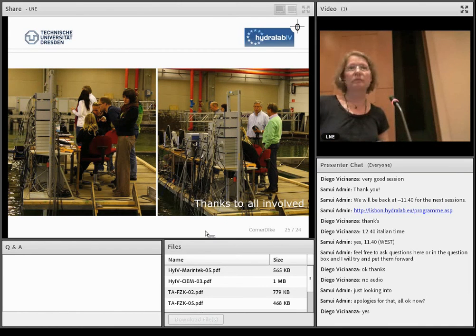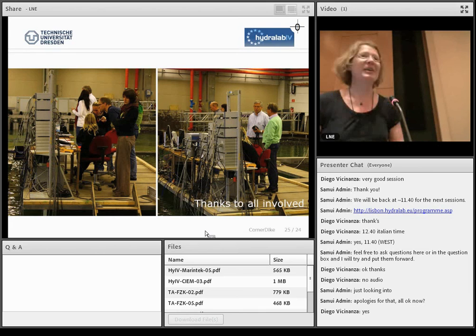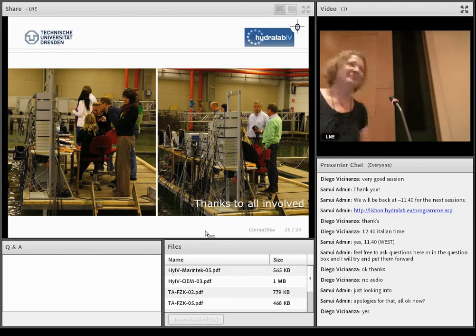My question relates to how you handle the varying water level, the storm surge level. I presume you keep the water level constant in your tests. For the run-up tests, we had only one water level of 70 centimeters, but for the overtopping tests, we had tests with different water levels, so different freeboard heights.